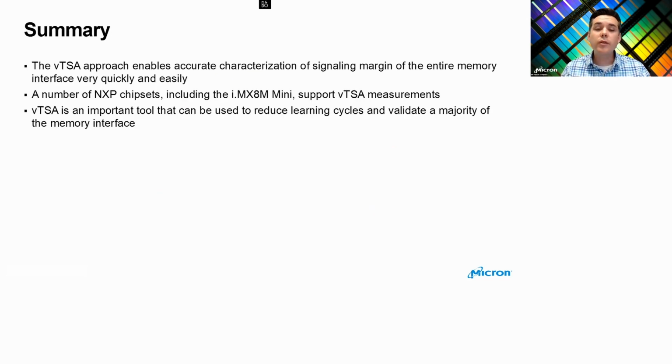So in summary, the vTSA approach gives you access to information about signaling margin on your system in a very quick and easy way. A number of NXP platforms support vTSA tools. The i.MX 8M Mini platform is one of them that supports it, as I showed today, but there are others as well. We at Micron really think this is an important tool to give you access to the information you need quickly and shorten your learning cycles, so that you can understand if you have marginalities early on in the process and get those addressed before it becomes a bigger problem.